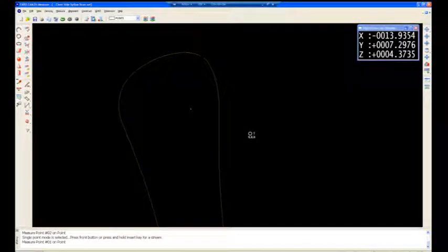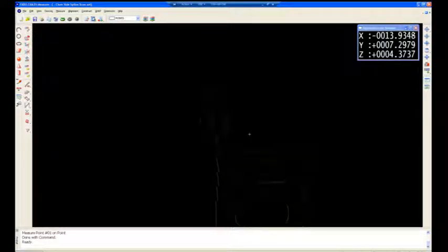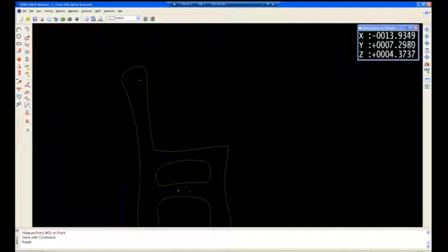Now let me zoom out. I'll hit escape on this first just to back out of doing more planar points. And now notice I've got those 3 points that will show up in my SAT file in this model right here. So when I do that, that center point location is going to be in a perfect spot for setting up a drill jig or some kind of a fixture, or even setting up an NC program that's going to come and drill in that exact location.